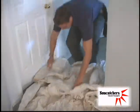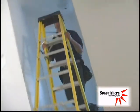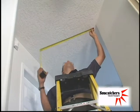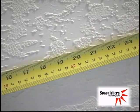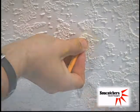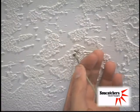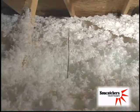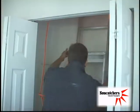Place a drop sheet under the work area and put a ladder in place. Establish the location of the skylight by measuring from side to side with a tape measure, and make a mark with a pencil. Use a stud finder to locate the nearest truss. Now insert a stiff wire that will go through the drywall and insulation to serve as a marker inside the attic.